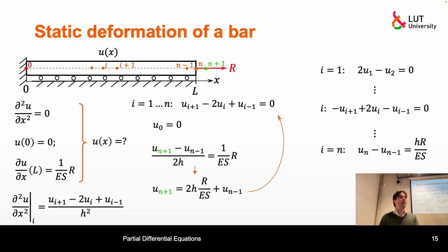Speaking in finite element terms, it's called an essential boundary condition. And essential boundary conditions may be not only Dirichlet boundary conditions. For some numerical schemes, derivatives may also be included in essential boundary conditions. That depends on our degrees of freedom, on the interpolation that we are using.